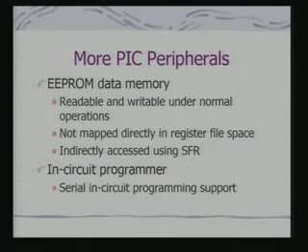Another interesting PIC peripheral is the EEPROM, the electrically erasable PROM data memory. So far we have discussed data memory as registers which were RAM area. Now, we are talking about electrically erasable memory. This provides you a facility for storing data even when the power is out, or in some cases when you have not operated the system and you want to record the status for subsequent debugging and so forth. These registers are readable and writable under normal conditions.